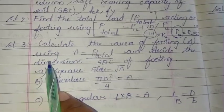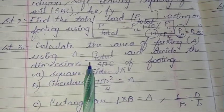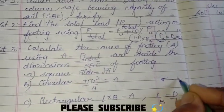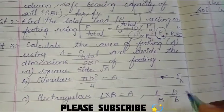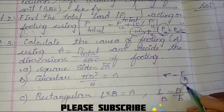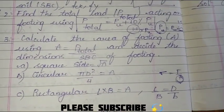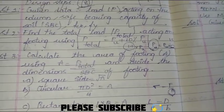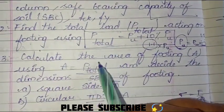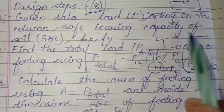So next, the third step is calculating the area of the footing. Firstly, stress equals force by area. We know this formula. So whenever we need to calculate the area, it is going to be area equals force by stress. Here the force is nothing but the load that is acting. We know the P total, right? And here we are also given the safe bearing capacity of soil.